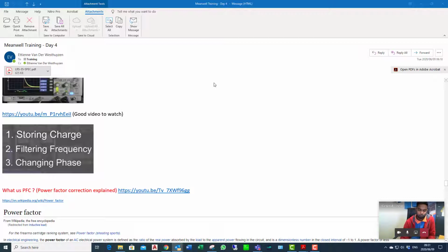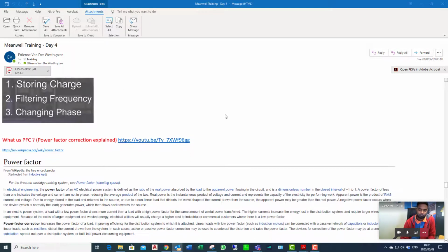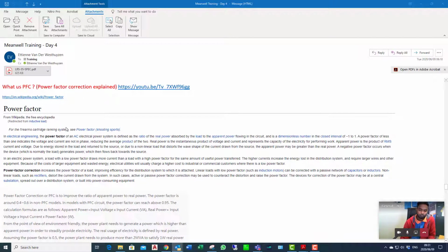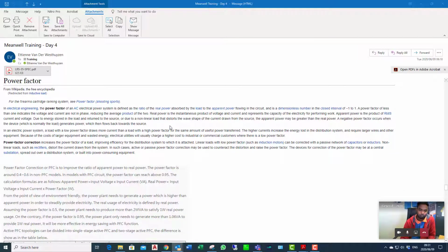You understand? So is 10 amps, have you added your safety factor or have you not added your safety factor? What temperatures are you going to vary? Where are you going to be putting your power supply? Is it an open cabinet? Is it internal? Is it external? Do you need conformal coating? All of those are information that you require. And one of the things we are going to be looking at is power factor as well. So I think it's very important.